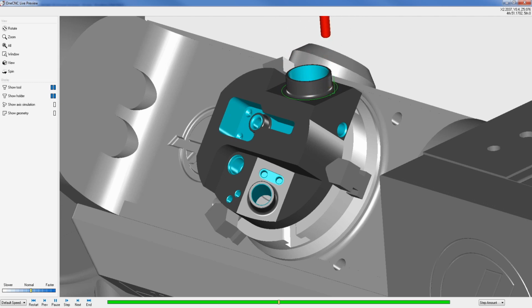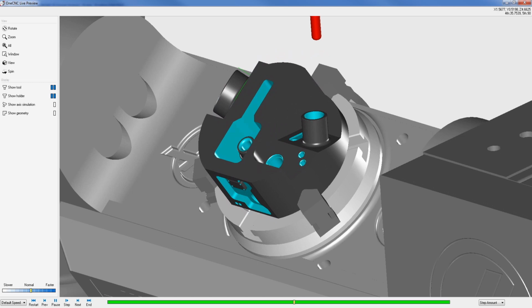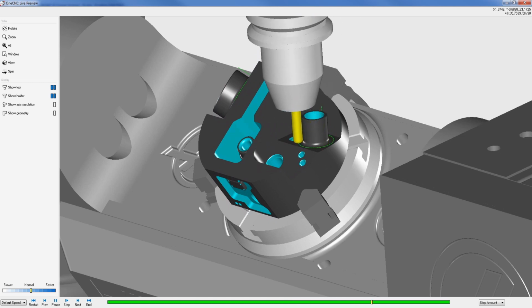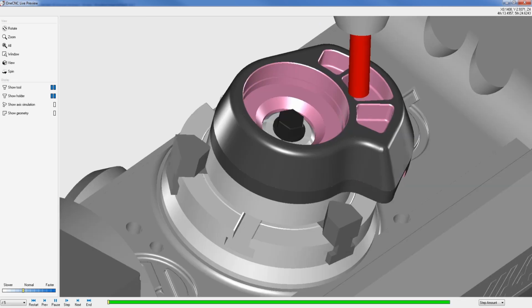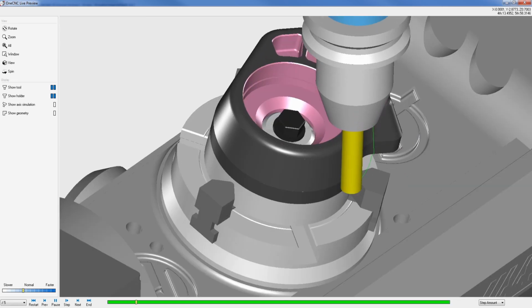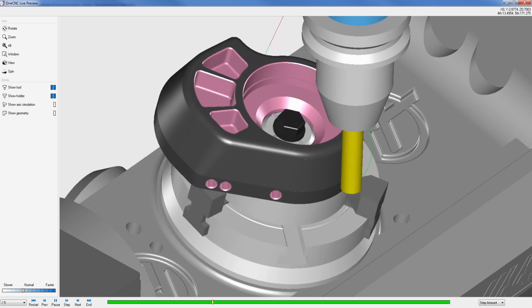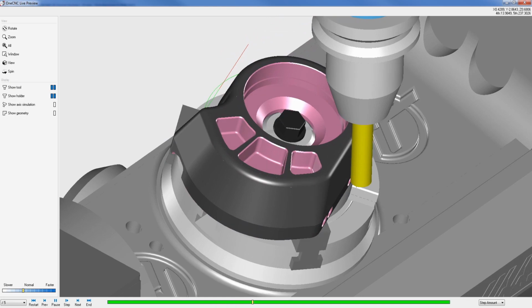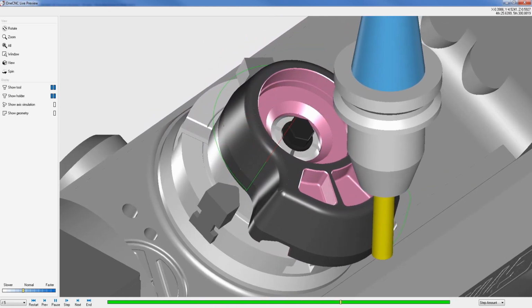Toolpath is applied to multiple sides of a part attached to a trunnion or using a machine tool that has an indexing head. Toolpath can be both 2.5-axis and 3-axis. OneCNC 5-axis simultaneous machining provides the very powerful ability to utilize all the axes when generating toolpath. In this example, we're using 5-axis swerve cutting to machine the tapered walls along the outside of the part.